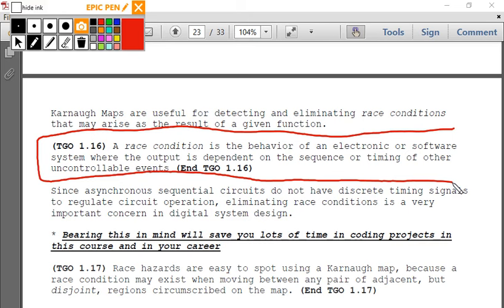It only takes its inputs and performs the operation, right? So we were talking yesterday about finite state machines. The D flip-flop's a finite state machine, right? It takes its input string, compares the input alphabet, performs an operation, compares to its memory element. So it's a Mealy machine, puts it on the output. But if the input's wrong, it's not the D flip-flop's fault.